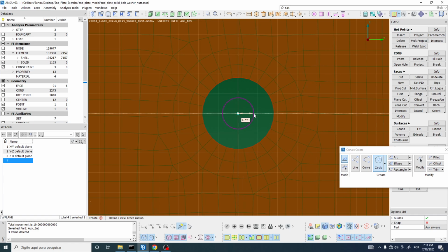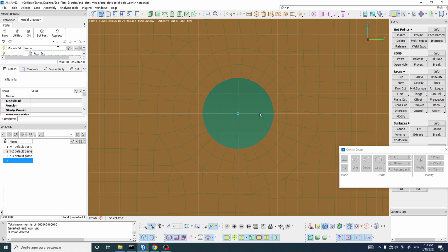Let's get this horizontal line, position the mouse here, space, and the radius is going to be equal to 10. I want the internal radius of this nut to be equal to the radius of the bolt. We know that in reality we have the thread of the nut, we have the thread of the bolt, but we are not going to model the thread of these two entities.